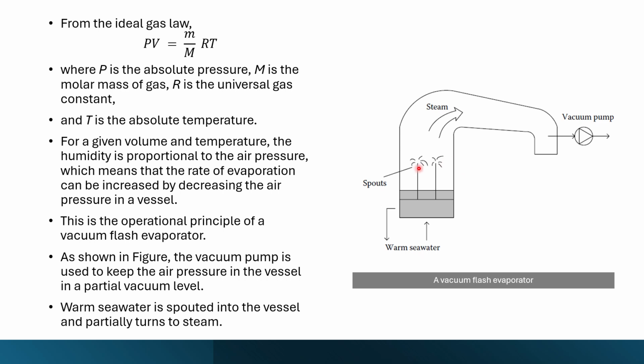In this model there is a tank and an absorber. The condenser works with the tank and absorber. The absorber has two inlets, one from the turbine and the other from the diffuser. The working fluid is a mixture of ammonia and seawater. In this simple model of the condenser, the transient performance is a function of temperature, pressure, composition, and mass flow rate of the working fluid.